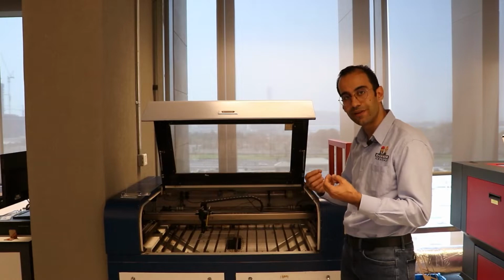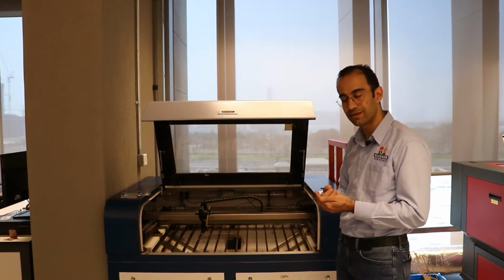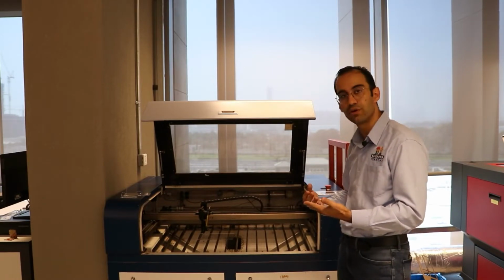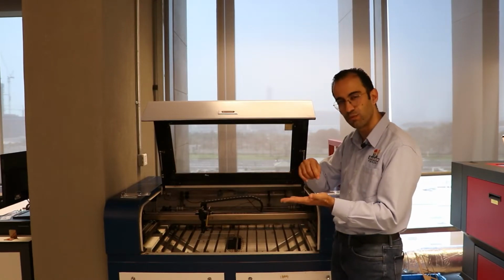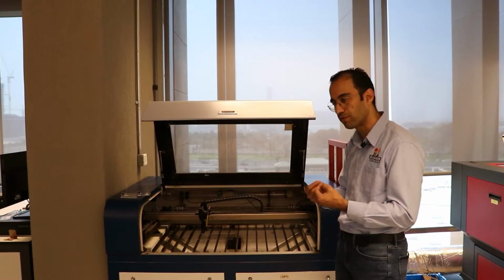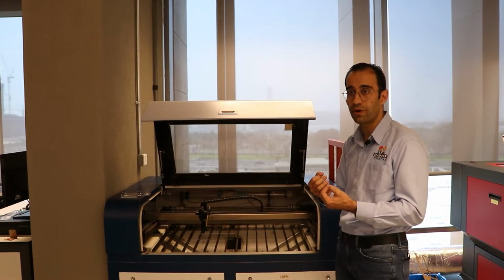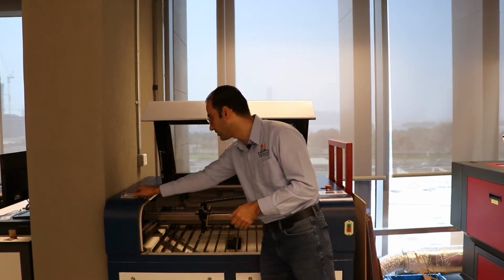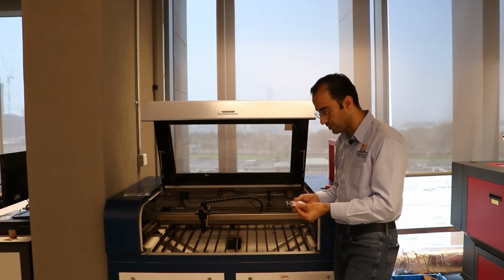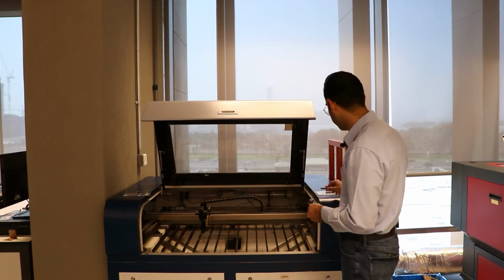It all depends on the laser power and the laser movement. So if you imagine you have high power or high intensity of laser that moves really slow, that's going to perform cuts. While if you have a laser that moves really rapidly, that will be more of etching the material, or engraving. And here I have a partially completed unit that we'll get to see how it goes very quickly here.